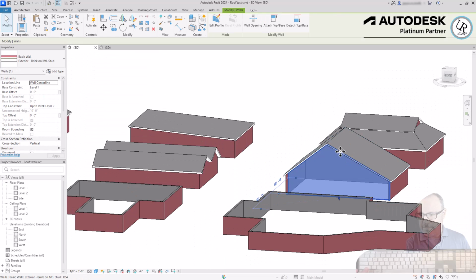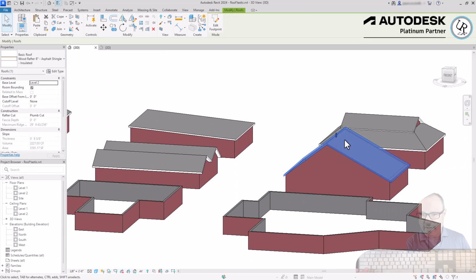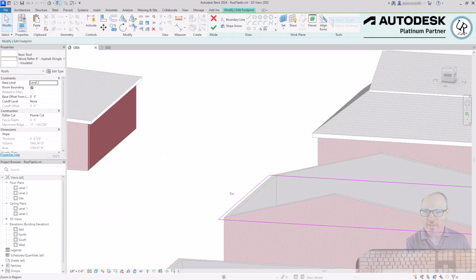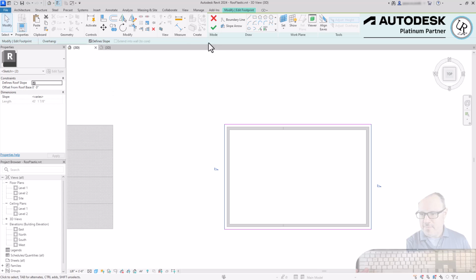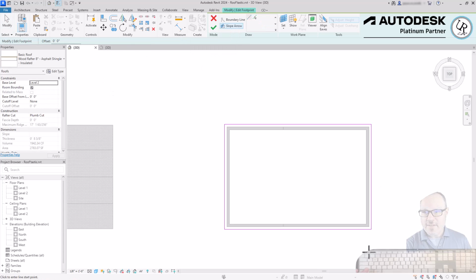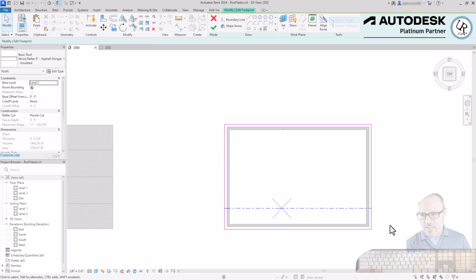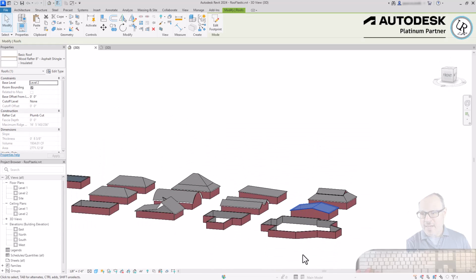And of course you can still select the roof and then change the height of the roof as well. Another one is to select the roof, again, delete all of the slope design, and then using slope arrows, you can actually employ more than one sloping arrow from one side to the other, where you have one side that is set up to, let's go with 4 feet on this side, and then up to 8 feet on the other side. And it will match up those roofs wherever that peak needs to exist, looking something like this.